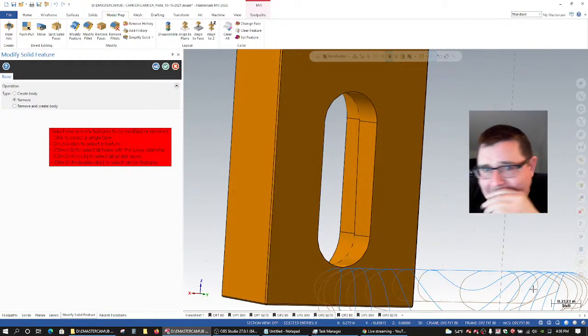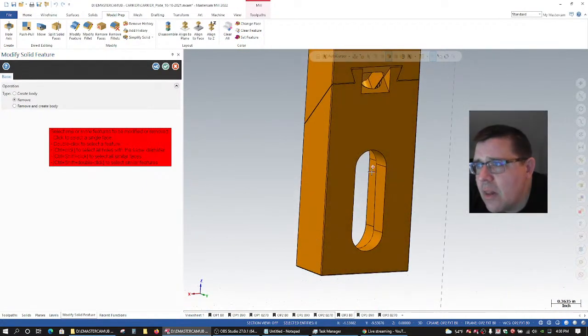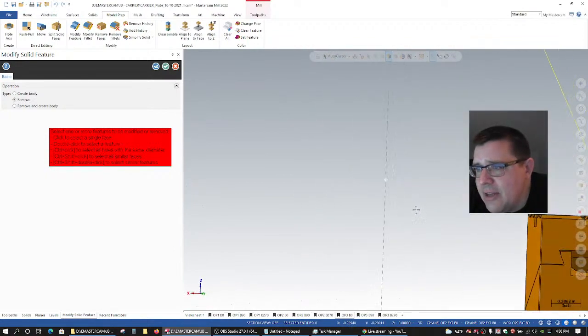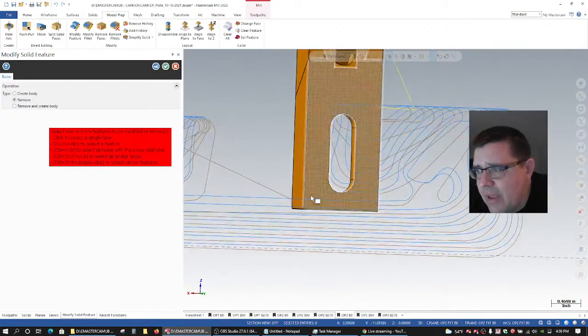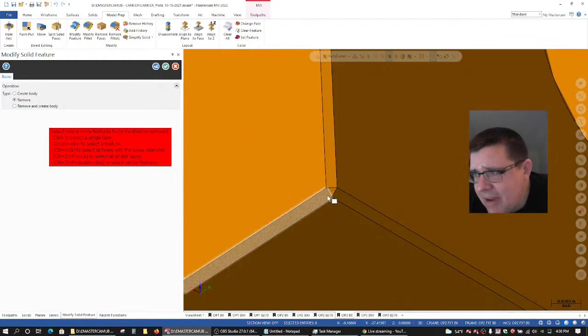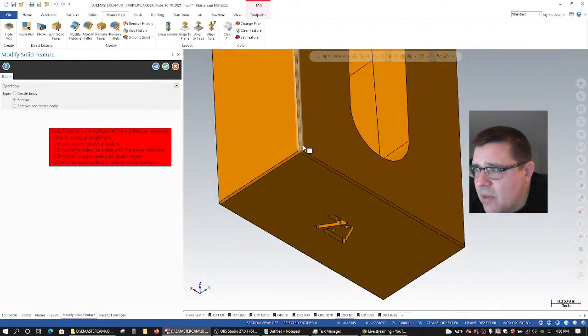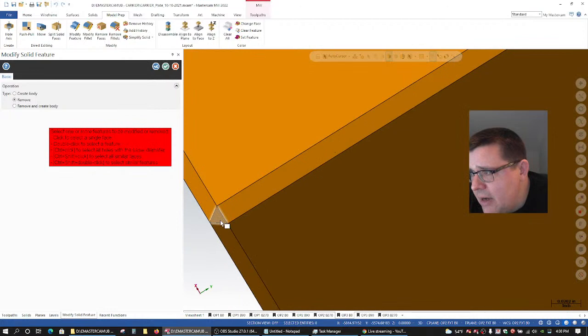And so what I do is I start to try and just remove the chamfers or fillets first. So for example, on something like this, I've got three corners meeting together. Try just removing the corner, right? You've got this little mitered corner.